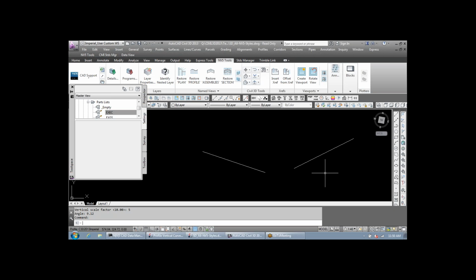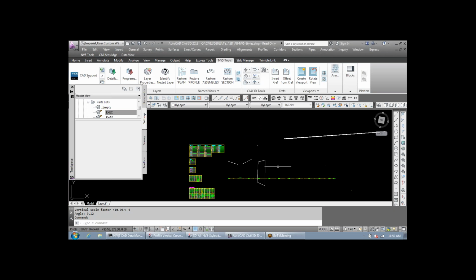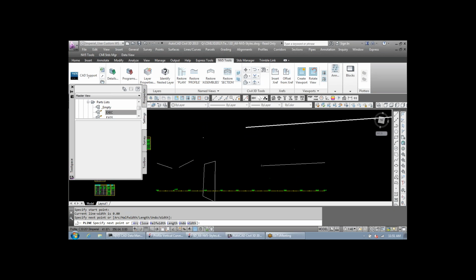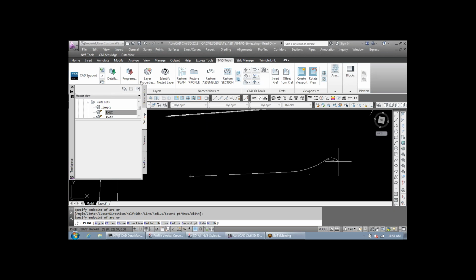The next one that is very important for everyone here is to check the tangency of your polyline before you create your alignment. A lot of times we'll have miles and miles of polyline representing our trench. And the last thing we want to do is click that polyline, create an alignment, and then get all these warning triangles at our curvature points.